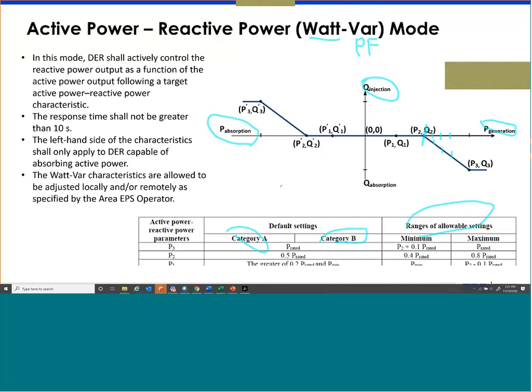The function is defined, but if you remember my previous comment, when it's charging, minimum reactive power capability is not a minimum requirement. So storage may not provide that, since there is no minimum requirement when it's charging. But if it offers that function, then that can be useful, because when you are absorbing power, most probably it will cause low voltage. So at a certain point, you may have to inject VAR to push the voltage high. So that's the idea here.